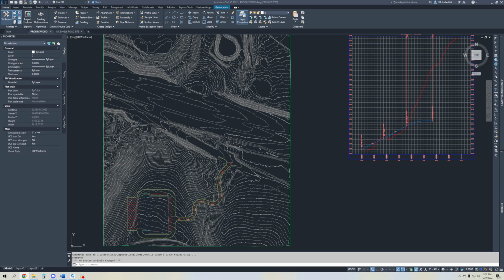If you have two feature lines that are touching at a certain point and they're on different sites, nothing will happen. But if they're on the same site, then they're going to want to grab elevations from one another, and they'll interact in a very weird way. You tend to get a lot of weird issues with your surface when you have two feature lines crossing that are on the same site. So that is a basic explanation.